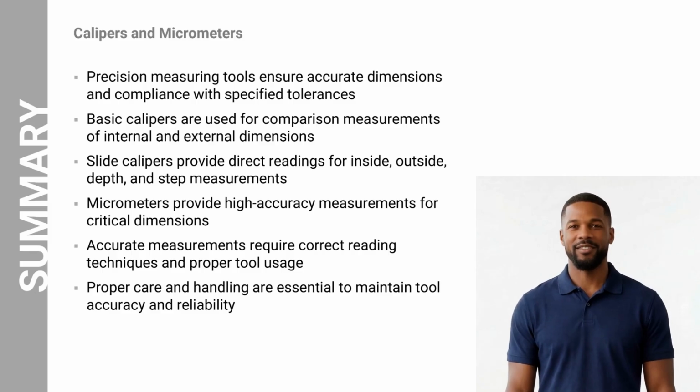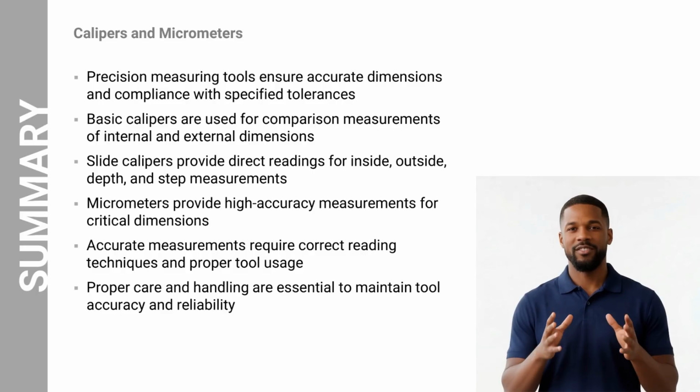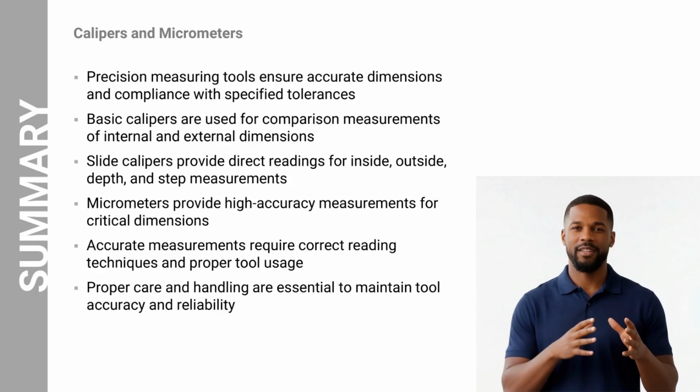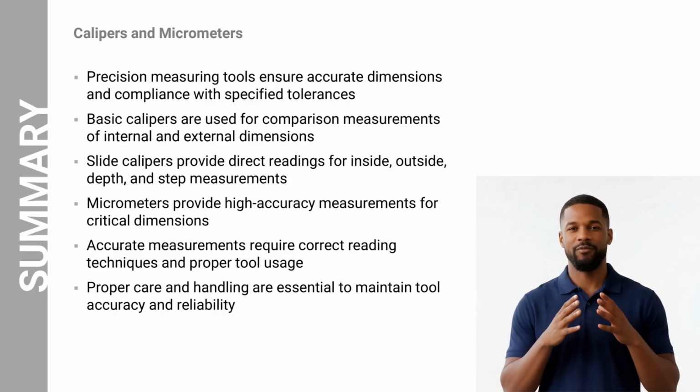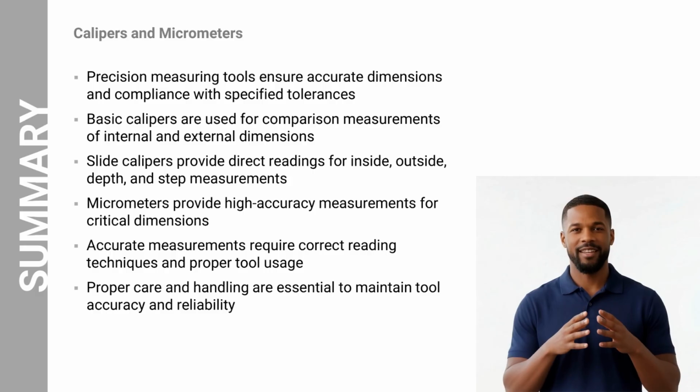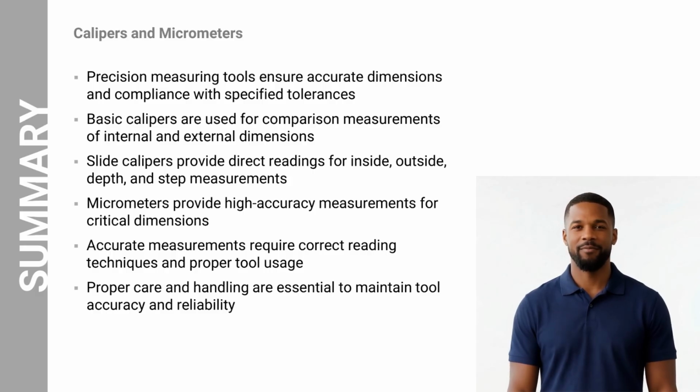Let us now summarize what we have learned in this lesson. Precision measuring tools are essential for ensuring accurate dimensions and compliance with specified tolerances in aviation maintenance. Basic calipers are used primarily for comparison measurements of internal and external dimensions, while slide calipers provide direct readings for inside, outside, depth, and step measurements.